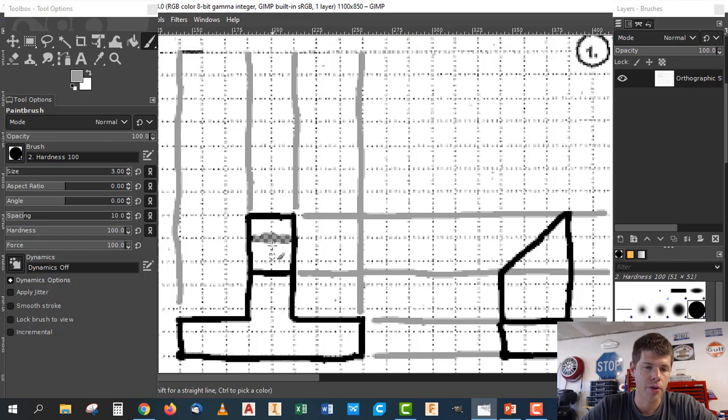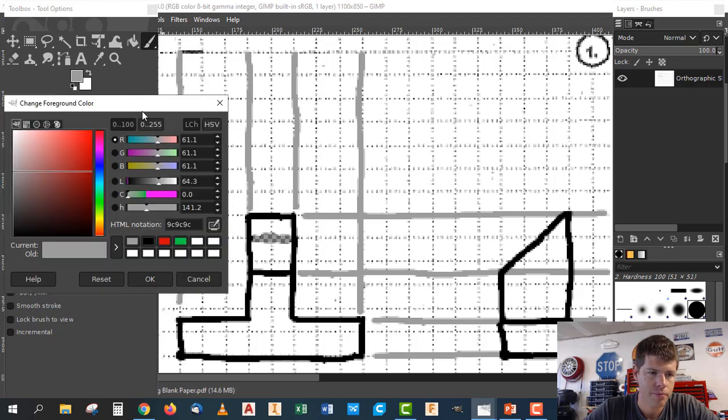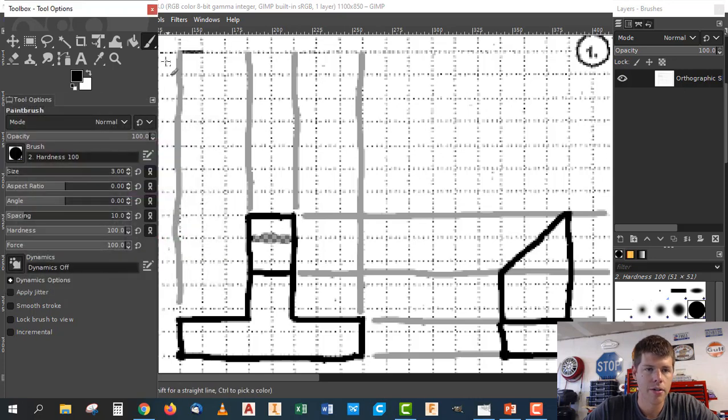So remember, in my front view I've got height and width, in my right view I've got height and depth, and my top view I'm going to have width and depth. So all the information is technically on here. We just got to make it match. So I'm going to put an arbitrary start point kind of right here.